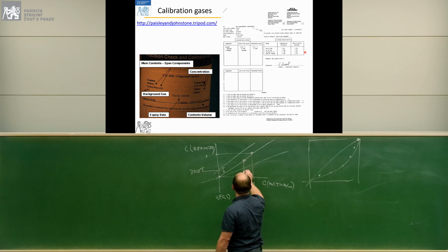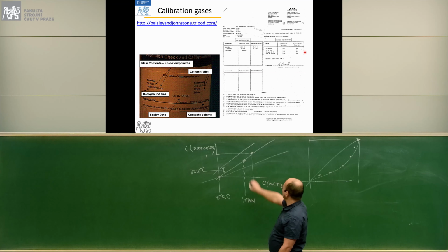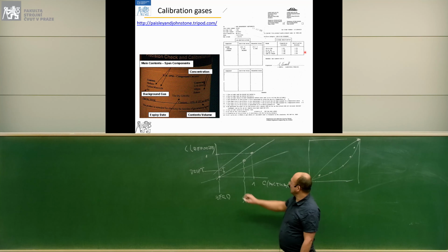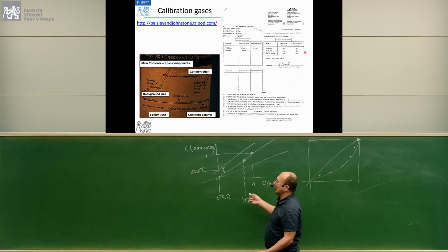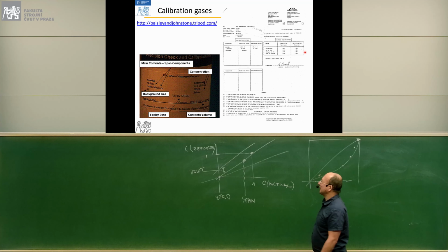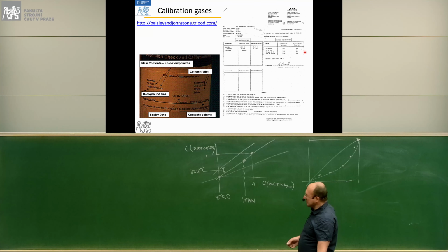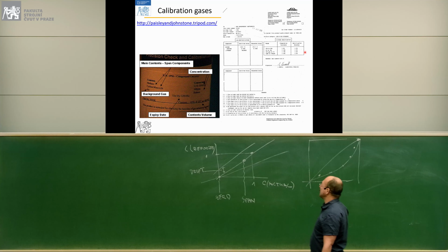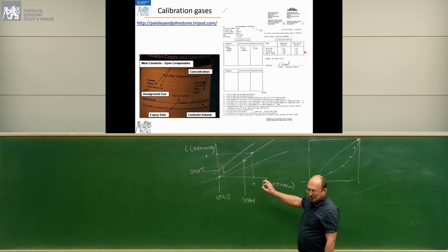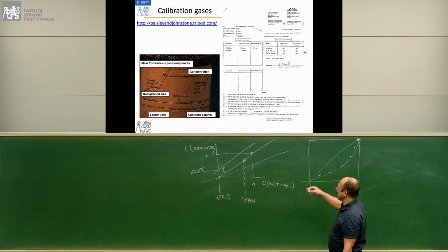Then you pick where you will be measuring. Typically at 80% of the range, you choose a concentration, and at that you do span calibration. So if the measurement range is, for example, 0 to 1000 ppm, then at about 800 or 900 ppm, you do span calibration. If the instrument has multiple ranges, sometimes it's good to do span calibration for each and every range. You do these daily, and sometimes before and after the measurement, to make sure that the calibration of the instruments didn't change.